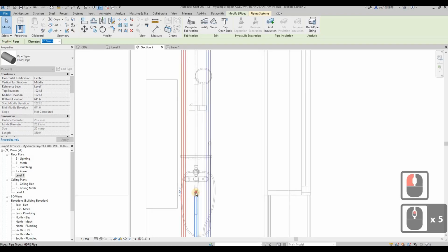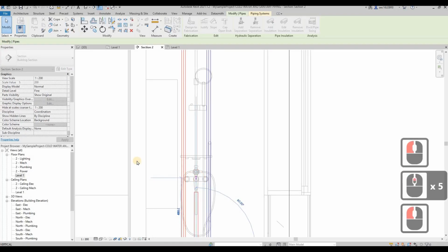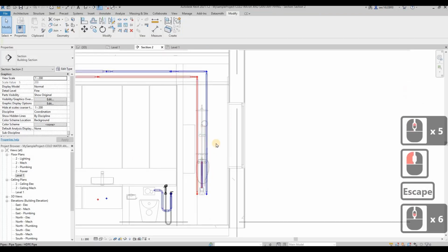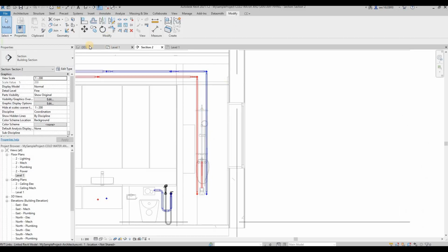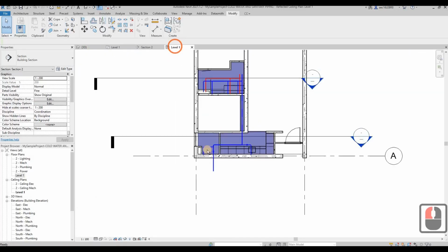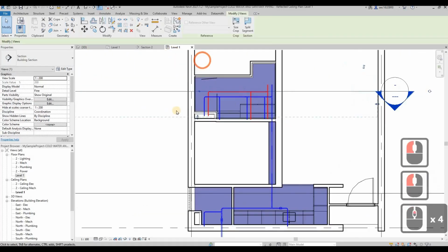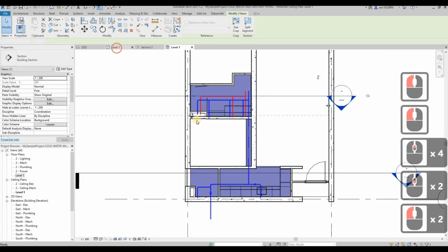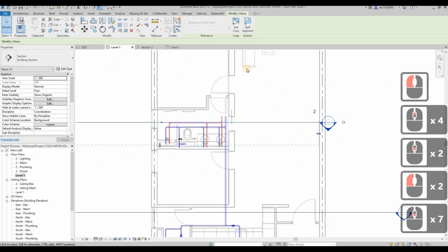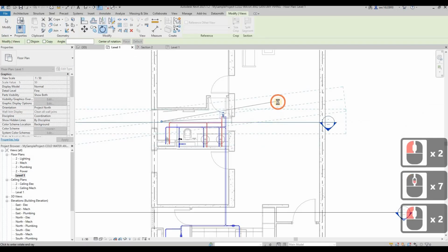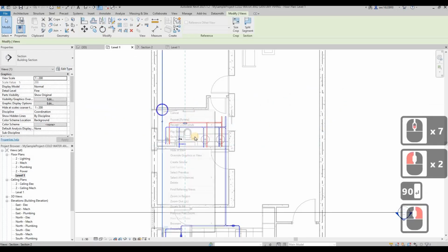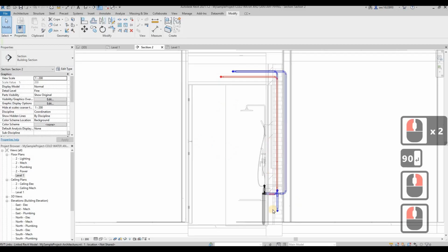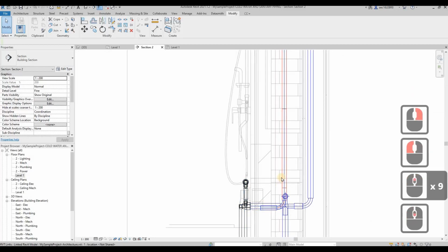So the diverter is here. I'm just going to stop it over here. Of course, for the detailed connection, you need to refer to this catalog. What should be the correct way of connecting this mixer? You need to refer to the catalog, okay? Then at the moment, we just roughly make a connection here to show you how to model the piping, okay?